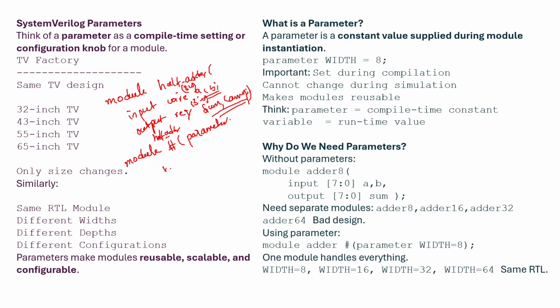In this parameter I am writing some width. Data width equal to, I am creating 16 bit. Then whatever data we are using, that will be applied for it. So data width, I'm using a semicolon in this. Again we need to open the brackets, and then input, we are taking a, b of width minus 1 down to 0.